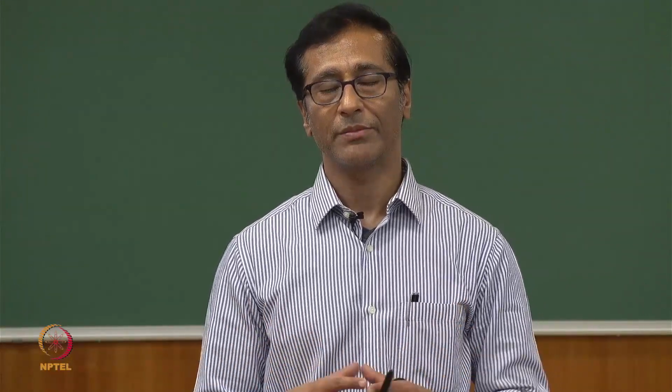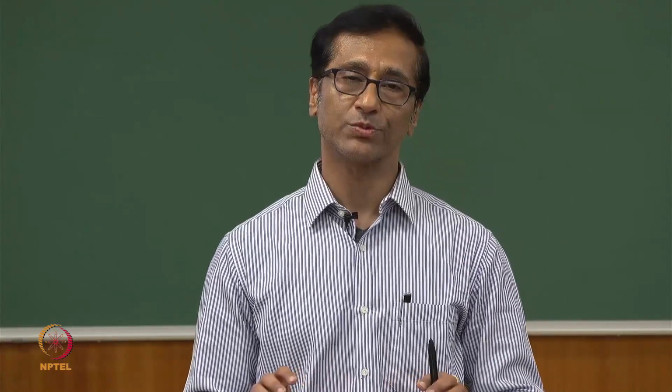These things are important. Now, when we talk about fracture mechanics, in my view there are many factors, but two very important factors. One is the stress intensity factor. What is a stress intensity? Can we really minimize the stresses? Surface roughness itself creates a stress intensity, or a concentration of stress at a few locations. That is why in our earlier lecture we said please keep a smooth surface, minimize the asperities, minimize the surface roughness. And of course, when we design a surface, when we think about coating and surface design, we will again be deliberating on this topic.